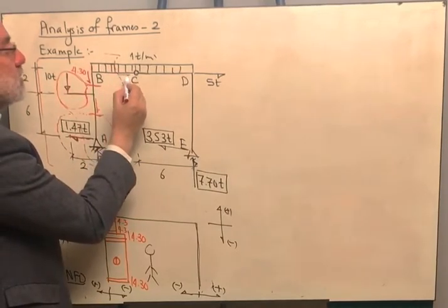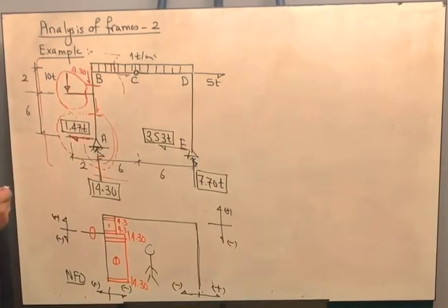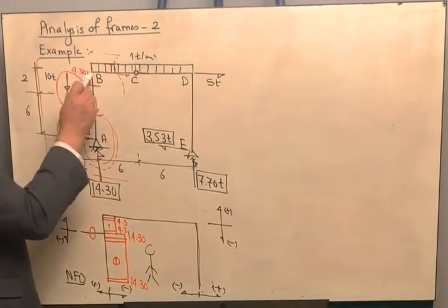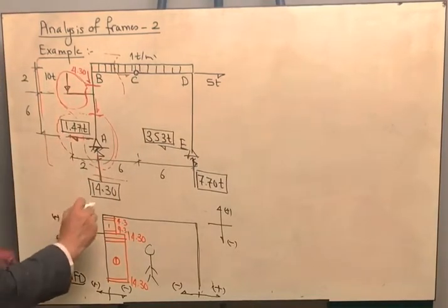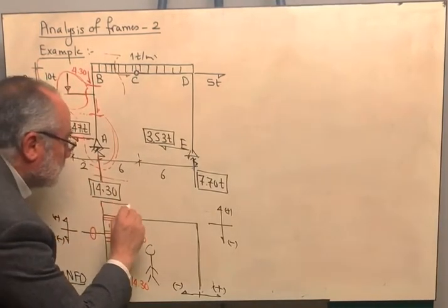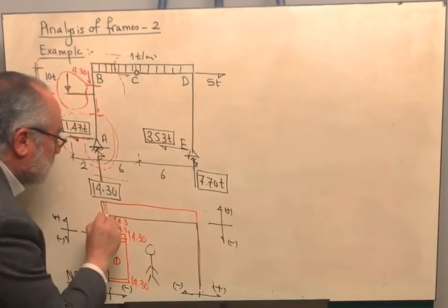It means that the internal force that should balance with it should be in this direction, it is causing tension. This condition will persist throughout the member BCD. Therefore I will have here tension constant.